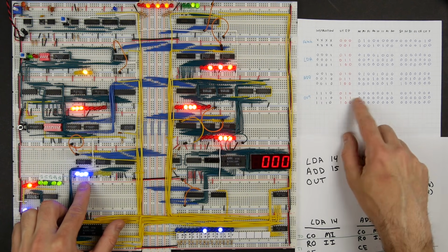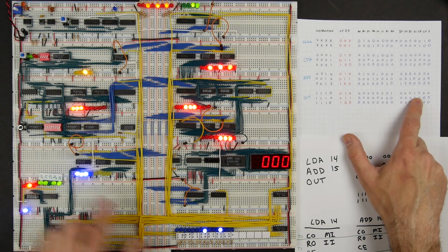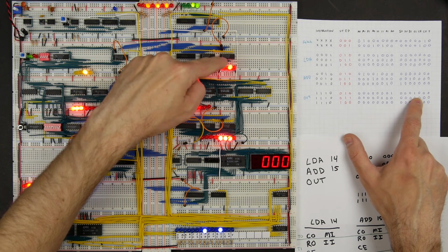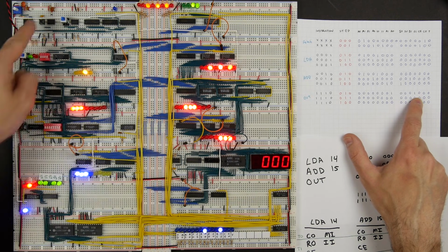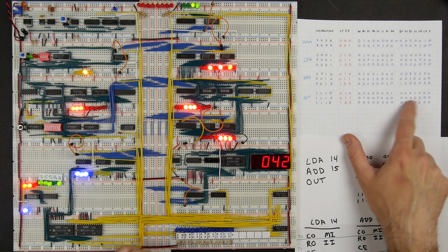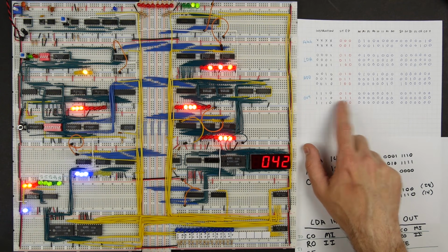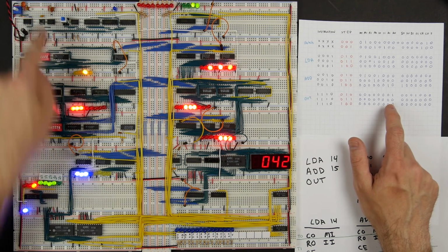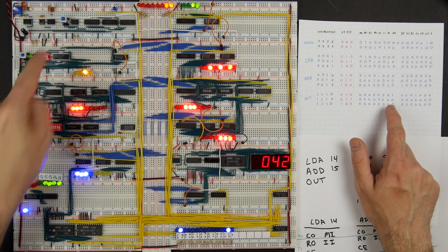And so now what we're going to do is we're going to say A out and output register in, and that's what we've got here. And so if we step this, it should take the contents of the A register and display it on the output. And there it is, 42 is the answer, as it should be. And the next 2 parts of output are just all zeros. So we've got all zeros, so that's a clock cycle, and then all zeros, that's a clock cycle, and we're